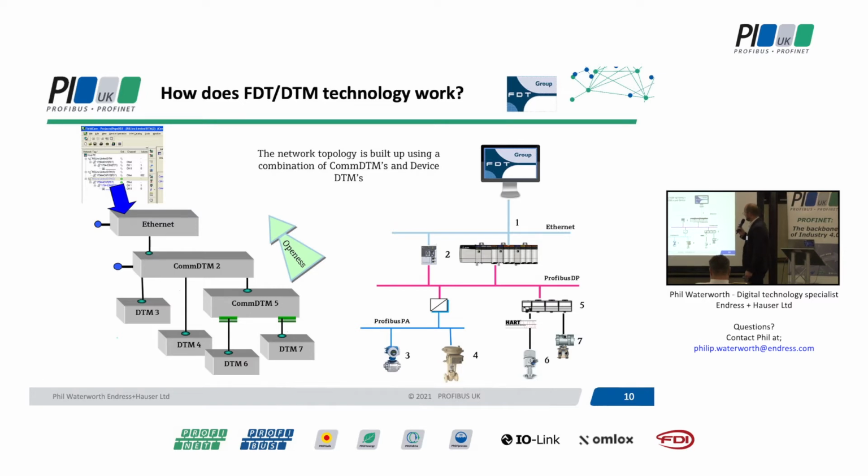Basically, from this top end, we want to be able to communicate to the devices at the bottom, some of which are on Profibus. We actually have some here through some Profibus remote I/O onto HART. So again, a nice mix of protocols, not uncommon in process plants in particular.